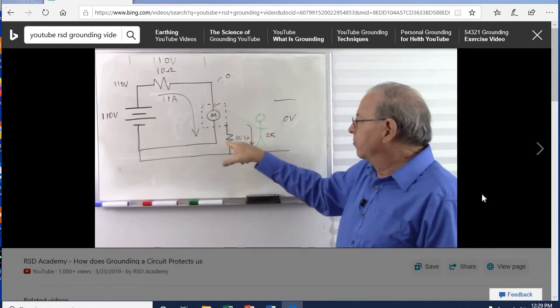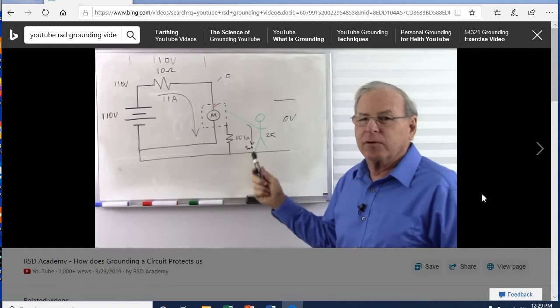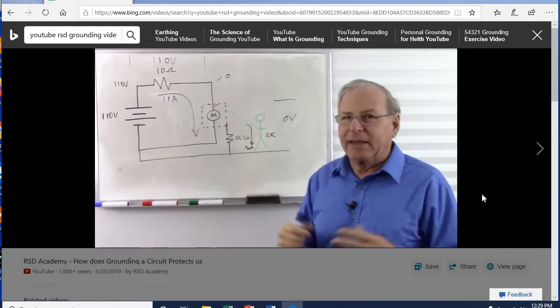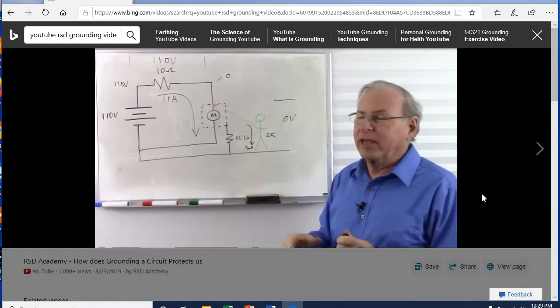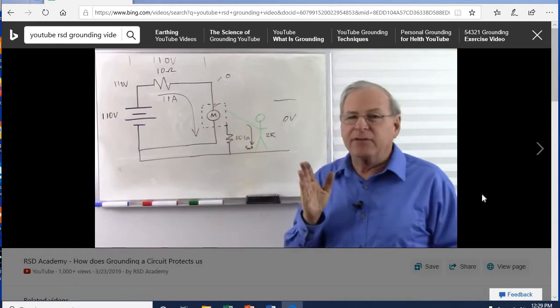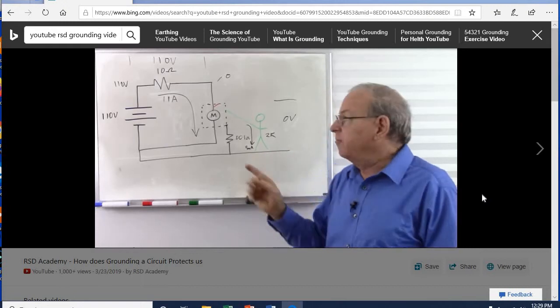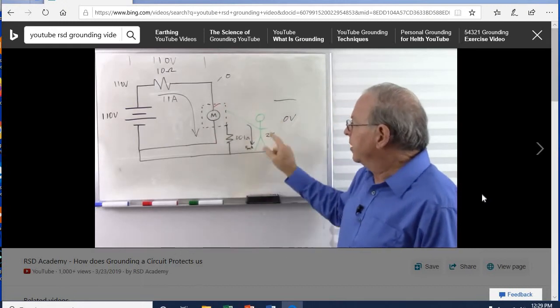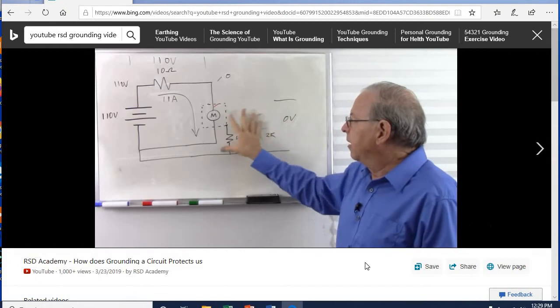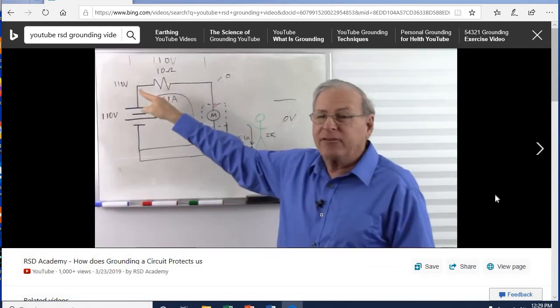Essentially 0 volts across essentially 0 ohms. I get practically 0 volts across it. So that's the way it works. Once again, just quick emphasis. I don't get saved because of the myth that electricity seeks the shortest path. I get saved because my total resistance, me and the ground, becomes so low that I get so much current through here. Here's where the magic happens.